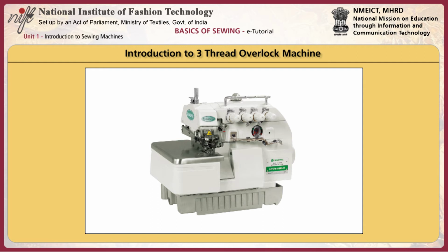An overlock sewing machine differs from a lock stitch sewing machine in that it uses loopers fed by multiple thread cones rather than a bobbin. Loopers serve to create thread loops that pass from the needle thread to the edges of the fabric so that the edges of the fabric are contained within the seam.